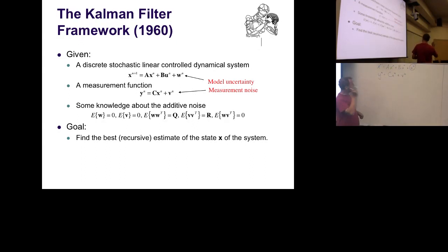Okay, super simple example. If I have a proper state which consists of position and velocity, so this is my proper state of a second order system, I can create an observable position state only by this matrix C. That would be quote unquote y. That would also be equivalent to x. So I can only observe x. This is what this equation says, nothing else but that. Okay? Now you can imagine how you can basically put things together. You could also put in differentiators in the observation equations and all kinds of stuff.